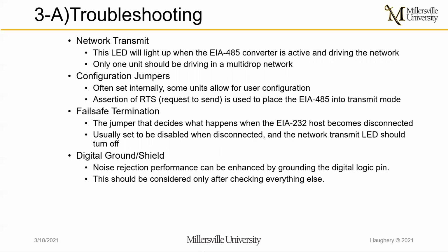For network transmission, this LED will be lit when the EIA-485 converter is active and driving the network. Only one unit should be driving a multi-drop network at a time, otherwise they will cancel each other out. For the configuration jumpers, these are often set internally. However, some units allow for user configuration.